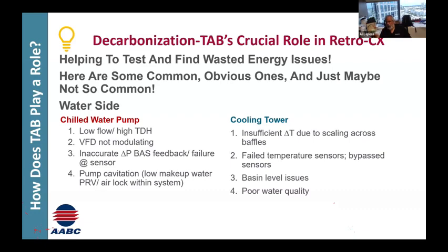One other thing on that, just from what I've seen: if the engineer didn't know what he was doing, and I say that with all due respect, I've met more mechanical engineers who don't know much about hydronics, and they oversize the pumps. If your pump is so oversized, it will roll out all the way on its curve, producing so much flow that it will cavitate because it's below the curve of the pump.